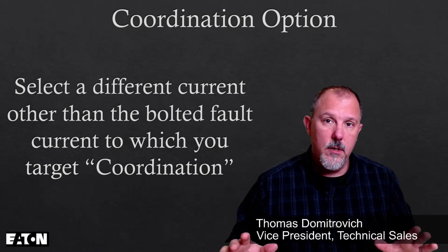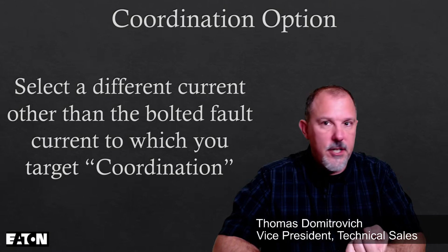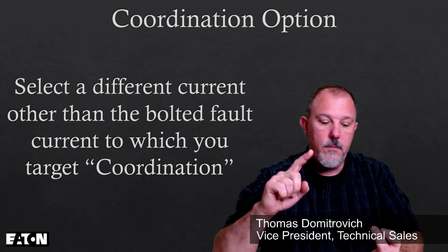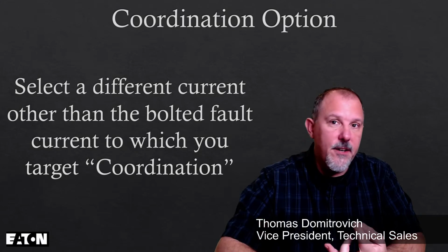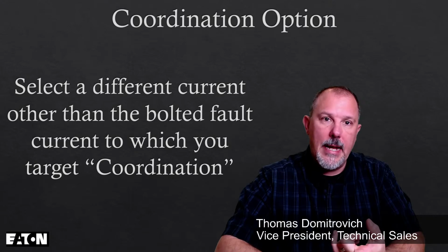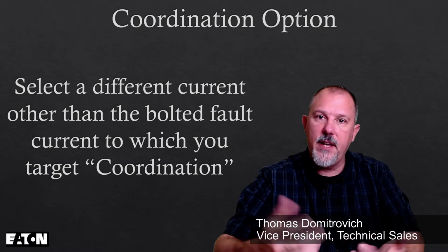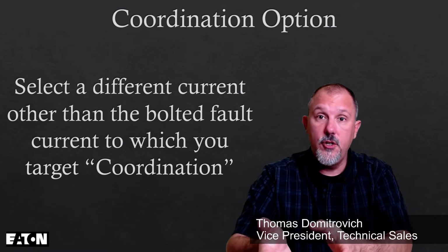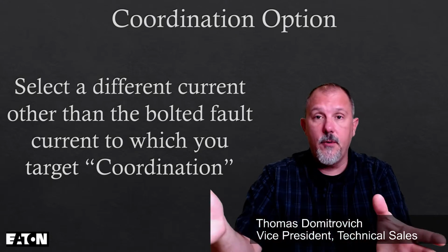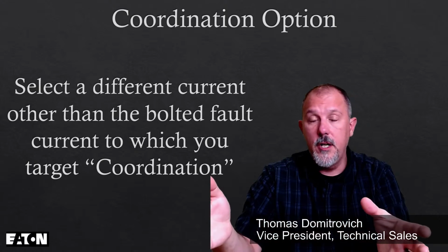But remember, from a coordination perspective, if that's all you're going for, you don't care about anything else, you don't need to hire an engineer. Use manufactured tables. You don't need to calculate fault currents. You'll probably not be into electronic trip units, and you'll probably not have to have arc reduction technologies, but you should do the evaluation. Obviously, I highly recommend doing an evaluation to determine your incident energy.